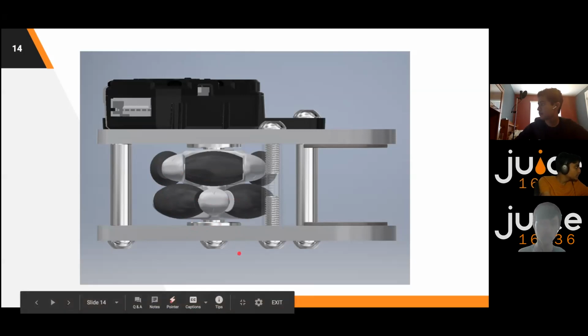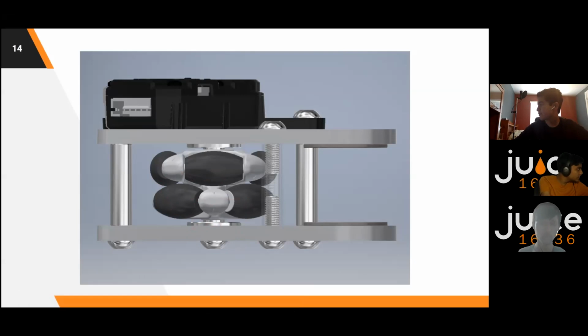Another person asked, odometry uses data provided from sensors. By sensors, do you mean encoders or something like a distance sensor? So odometry almost always uses encoders, like the encoder we have in that picture, but you can use PID with other types of sensors. For example, we used PID with just our motor encoders once, and we also considered using it with something like an ultrasonic sensor, measuring the distance from something.